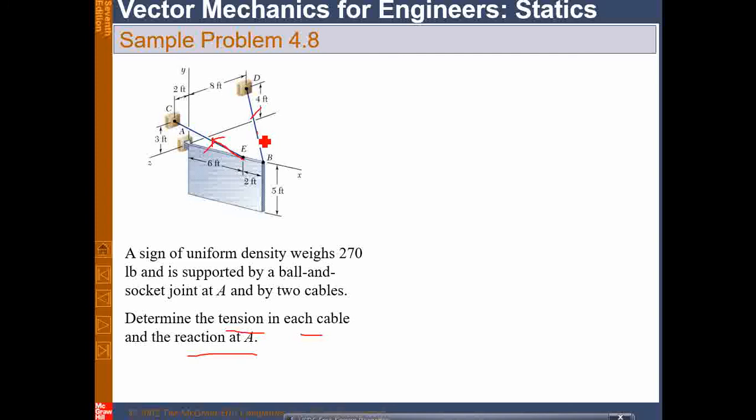So you need to find the unit vector for this. Brush up your lecture 2 and lecture 3, or lecture 4, where you will learn how to find the unit vectors along these two strings, and as you get the unit vectors, you will be able to obtain the forces. Once the forces are obtained, resolve these forces along the components.